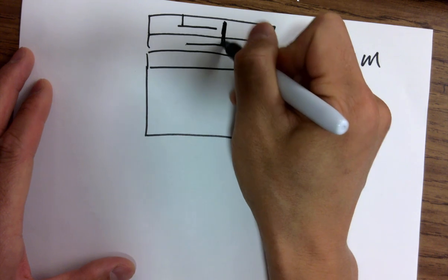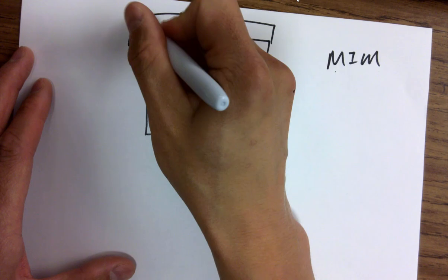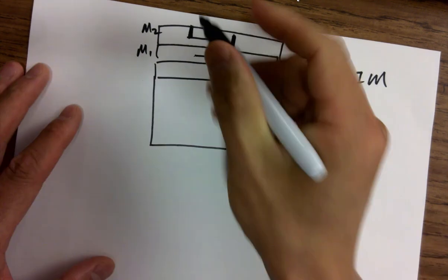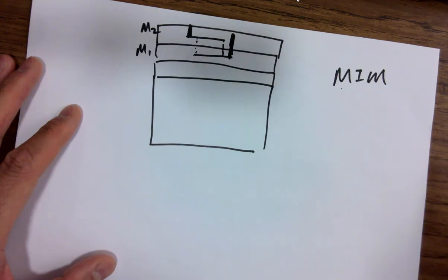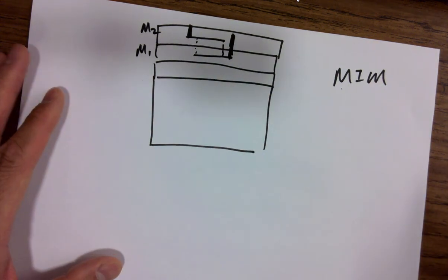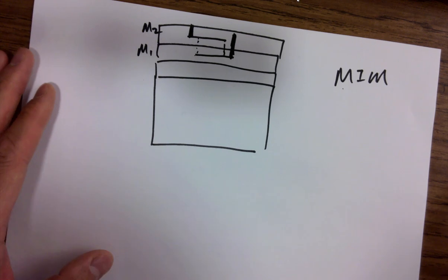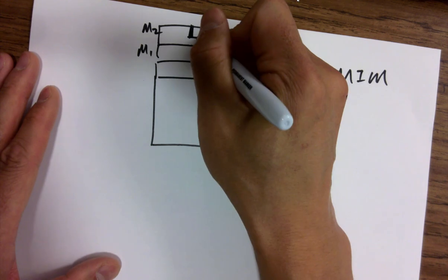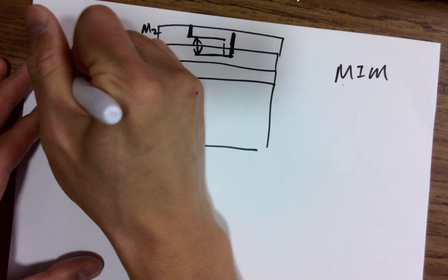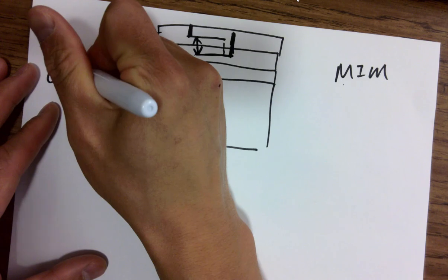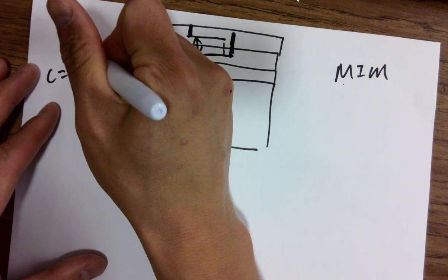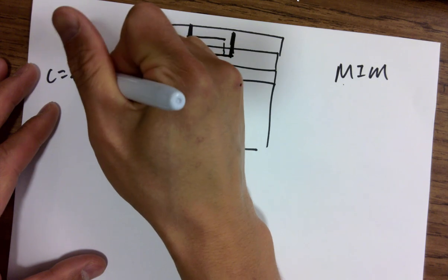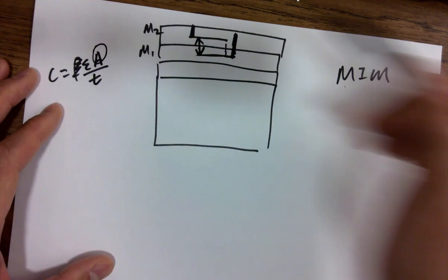I drew a via here, and that's metal 1, that's metal 2. So metal to metal is two metal plates, and we just look at the overlapped area over here to form the cap. Does that make sense? So in your layout, you lay out the metal 1. Can you change the distance, the thickness of the capacitor? Capacitor C equals sigma, no, epsilon A over T, because larger area is larger capacitance.